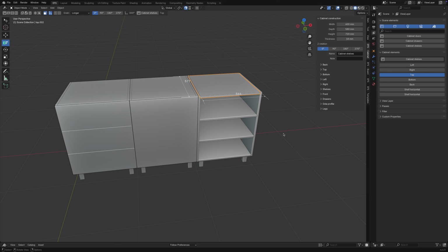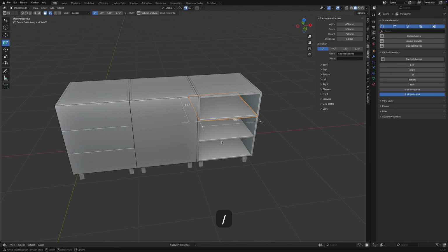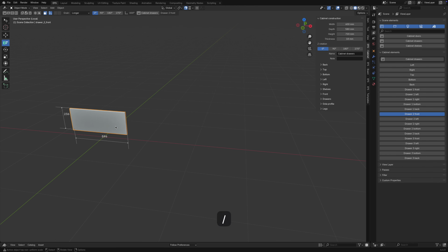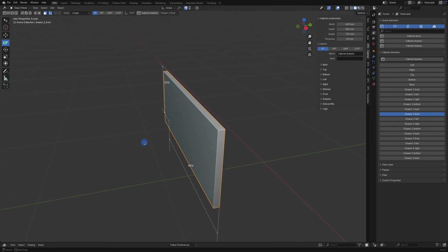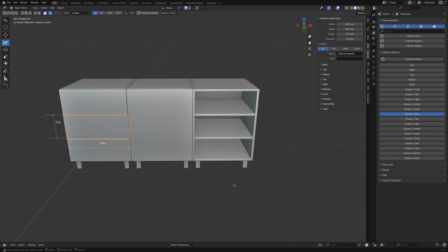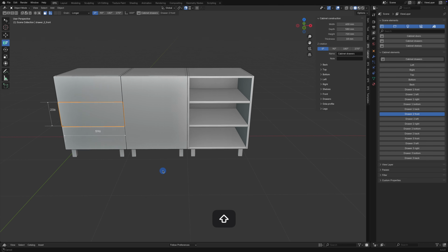When your design becomes complex and the screen feels crowded, you can isolate and examine just one object by pressing the slash key. This is particularly useful when you need to inspect detailed features, such as checking if a cabinet back is rebated or grooved. Press slash again to return to the normal view with all objects visible. To move around the view without rotating, click on the hand icon and drag while holding, or use the combination of Shift plus middle mouse button while dragging.